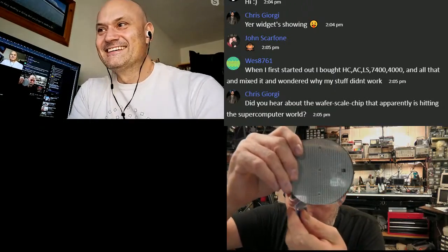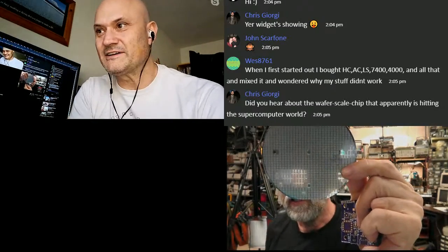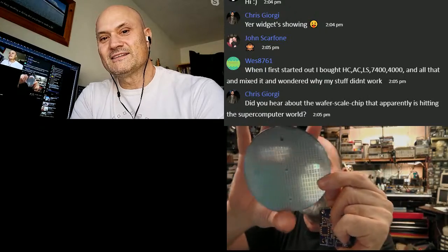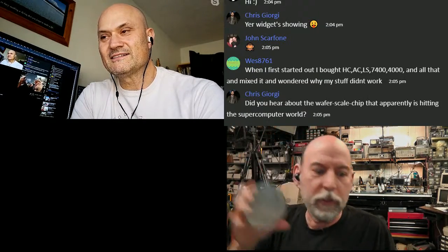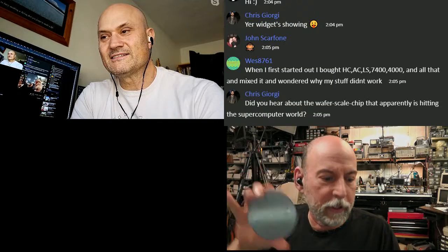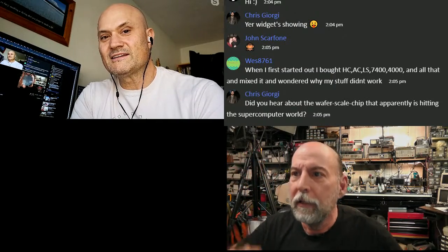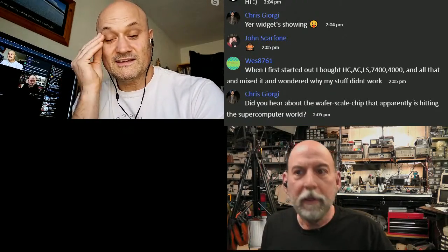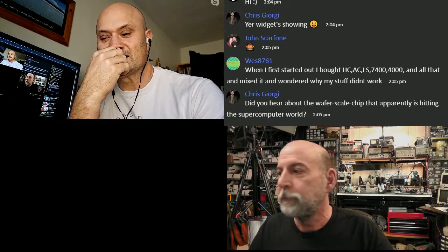But there's a flat edge here. I don't know if you can see it. It's machined flat on that side of the ingot, but it coincides with the crystal lattice. So that flat edge tells you the orientation of the crystal lattice, which is really important when you go to scribe these things. And by scribing, we do it just like glass. It's just like it sounds. That's for separating each die, or dice, from the wafer.